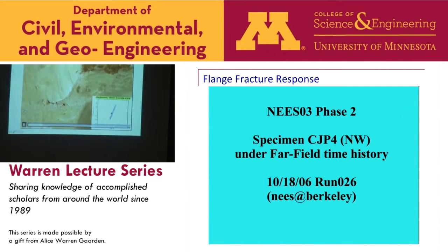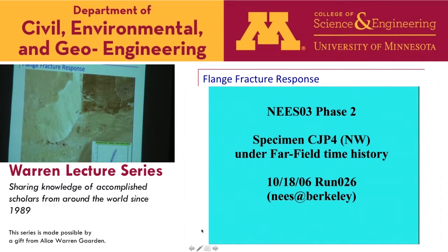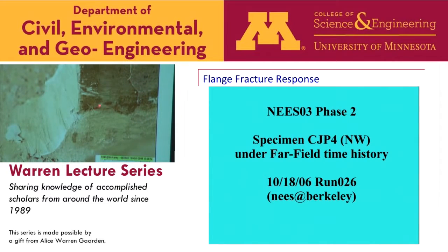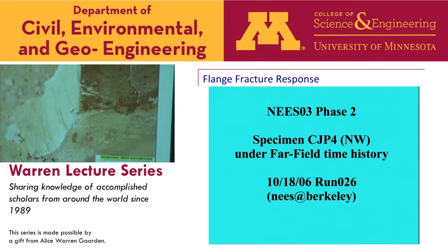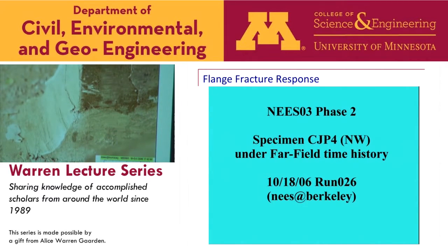Okay, so this is a zoomed in picture. This is the flange. This is the weld metal, the cyclic loading. This is the base plate down here. That's the mill scale flaking off. And we think it's right around here that the crack was initiating, with multiple cameras looking at that. Notice this crack is growing, even though it's visible, it's not affecting the overall load displacement behavior a lot.